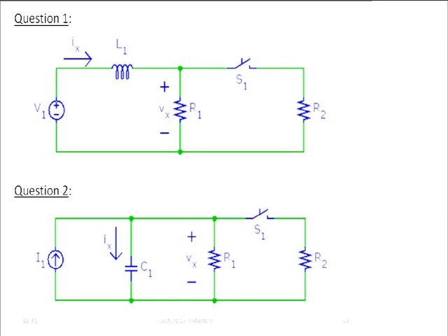You should be able, using node voltage analysis techniques, for example, or basically KVL and KCL, to write a differential equation for any kind of circuit. But we did not go through the mechanics of how to solve this differential equation, except for the first order. First order, where you just get an exponential increase or an exponential decay, that we talked about how to solve, and that you should be able to do.